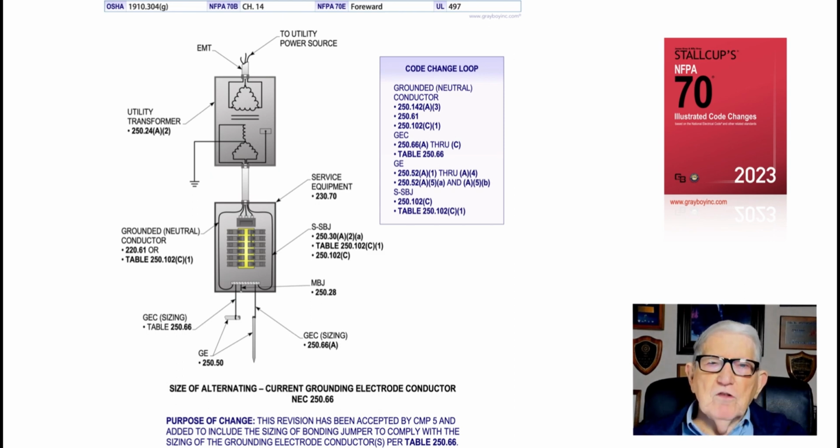The grounding conductor, you have your sections. The grounding electrode conductor, there are your sections. The grounding electrode itself, the system, then you have that list, all the sections listed. And then the system supply side bonding jumper, you have those sections listed. Can't go wrong. But this is a wonderful case study when you're grounding the service.